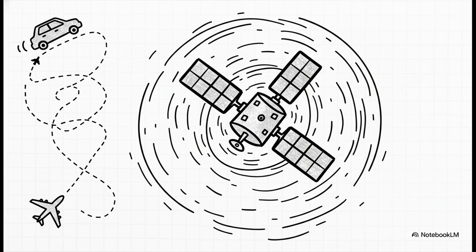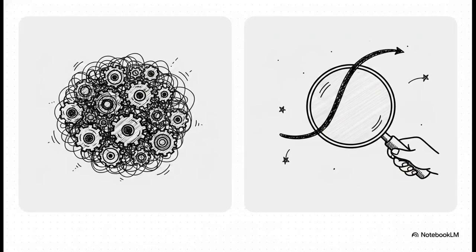Whether we're talking high-speed robotics or massive power grids, if the closed-loop system goes unstable, the physical hardware fails. It's really that simple. And this perfectly illustrates our problem solution framework here. To ensure stability, engineers have a few mathematical tools at their disposal. You've got the root locus method, which focuses on finding the exact closed-loop poles. But man, for highly complex systems, or systems where you only have experimental data, that can be mathematically exhausting, if not totally impossible. That is exactly why we turn to frequency response methods.